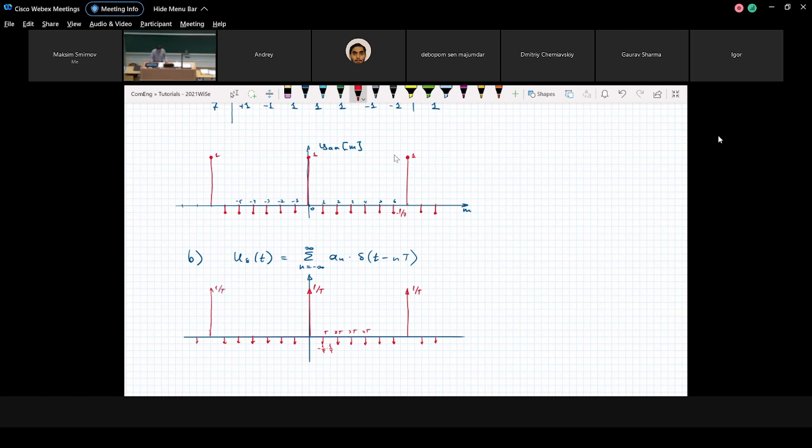This is our autocorrelation function of tau. Okay, great. Most important, find the discrete time autocorrelation function. And then after you normalize amplitudes by the spacing between delta pulses and replace indices by the spacing between delta pulses, you get the autocorrelation function of this sampled signal.